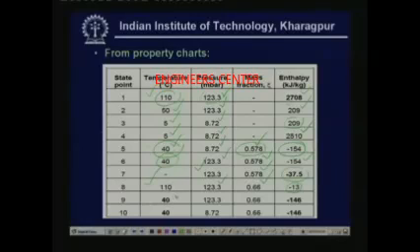Point 9 is the exit of the solution heat exchanger, and from the solution heat exchanger effectiveness of 0.6 we find that this temperature is 40 degree centigrade. So, we know the temperature and we also know the mass fraction. Using the equilibrium HTX chart, from this you can find the enthalpy, which is equal to minus 146.